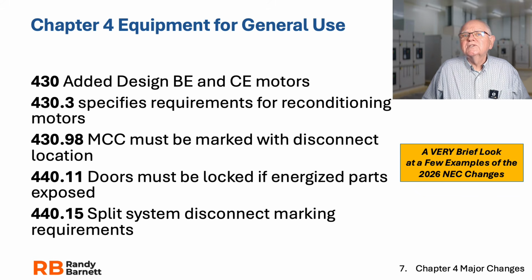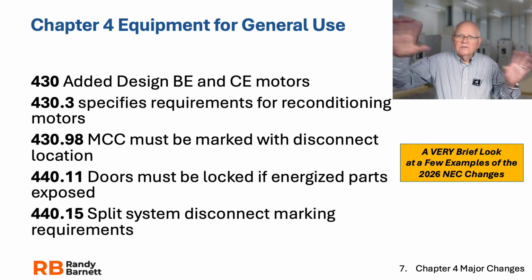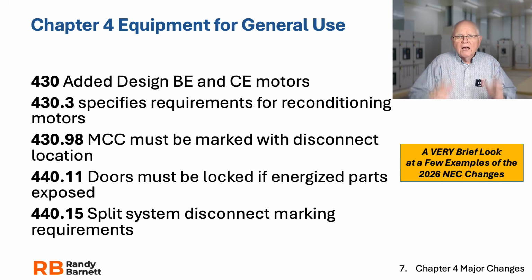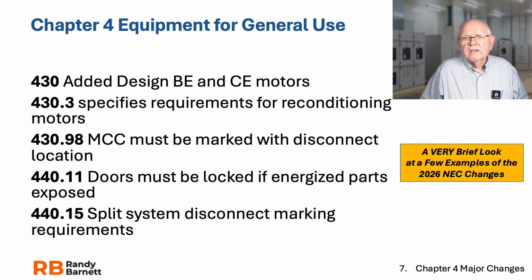Split systems, okay, and HVAC equipment. So our split systems, disconnect marking requirements. Makes sense. I've got a split system. I've got two different pieces of equipment. I have a requirement now for marking the disconnects for that equipment, 440.15.